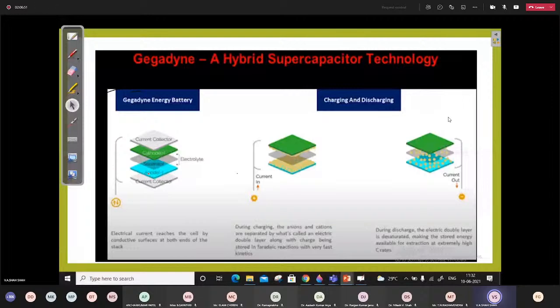So in that case, we may go with the hybrid energy storage system for vehicular applications in which this is a supercapacitor. We have different topologies. This is a semi-active topology in which the supercapacitor is connected with a bidirectional converter, and then the battery, all three connected in parallel. So the DC to DC converter will maintain the same voltage as the battery voltage, and then power will be supplied to the motor. In that case, we have to select which device will supply power, supercapacitor or battery.